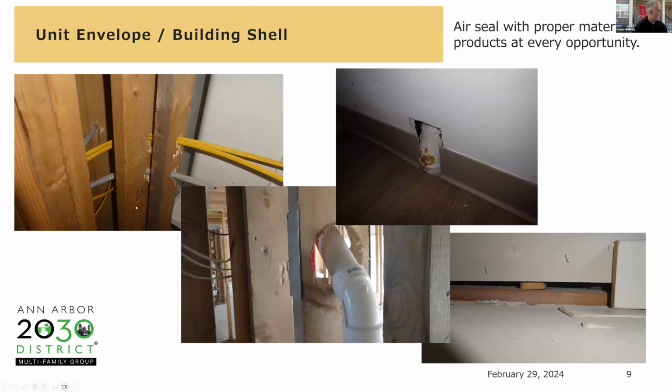And then here, like I was saying earlier, air can move through a building very easily through all the penetrations. So in this upper left picture, towards the left-hand side of it, that's an exterior wall, and the right-hand side of the picture is an interior wall. We can see how the wiring, the penetrations or the holes that the electrician has to make for the wiring to be pulled through, allow air to move through an interior wall. And behind it is a bathtub.